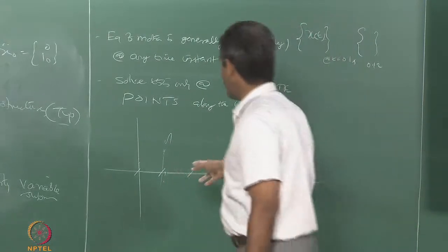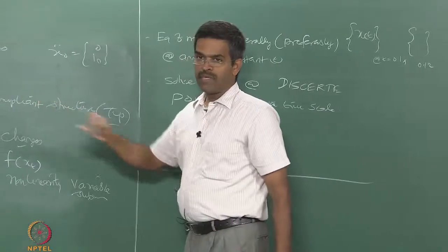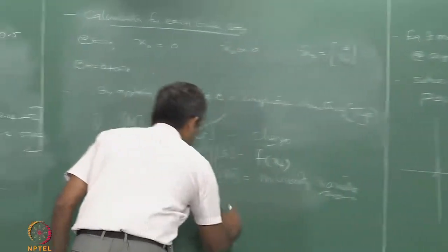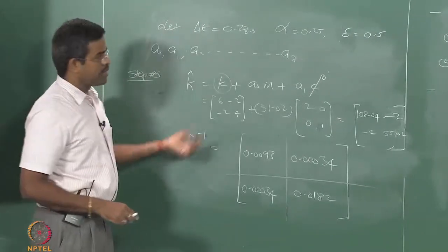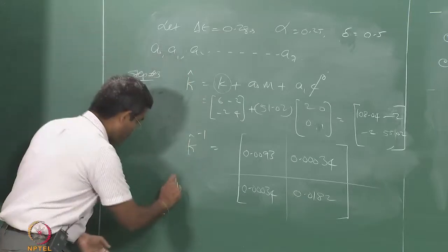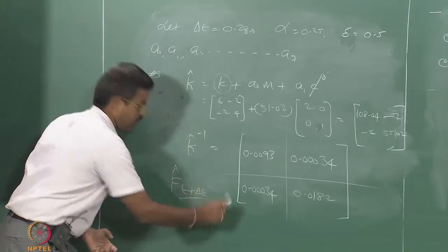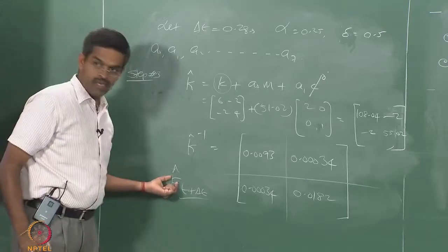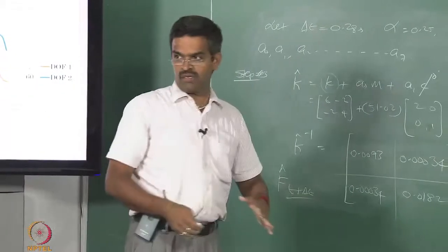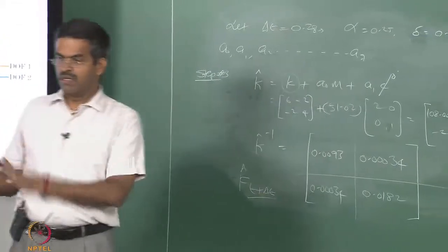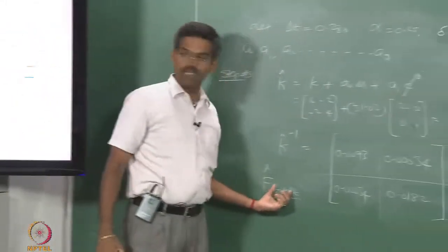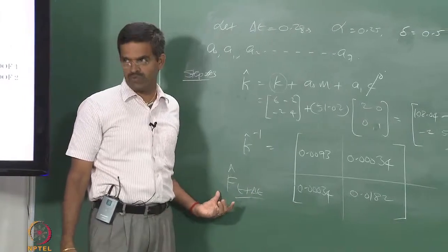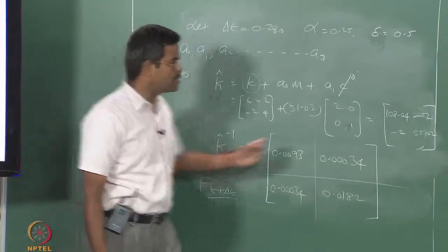Okay. So this problem will be there in case of compliant systems. And an additional problem: in all the schemes, if you see the whole issue, K hat or x of t, there is a divider at F hat t plus delta t, whereas F is also dependent on x, because in the Morison equation I have x dot minus u dot, a relative displacement. So if I do not have the acceleration at t plus delta t, I cannot actually find the Morison force. Okay. This will also come into the loop again here.